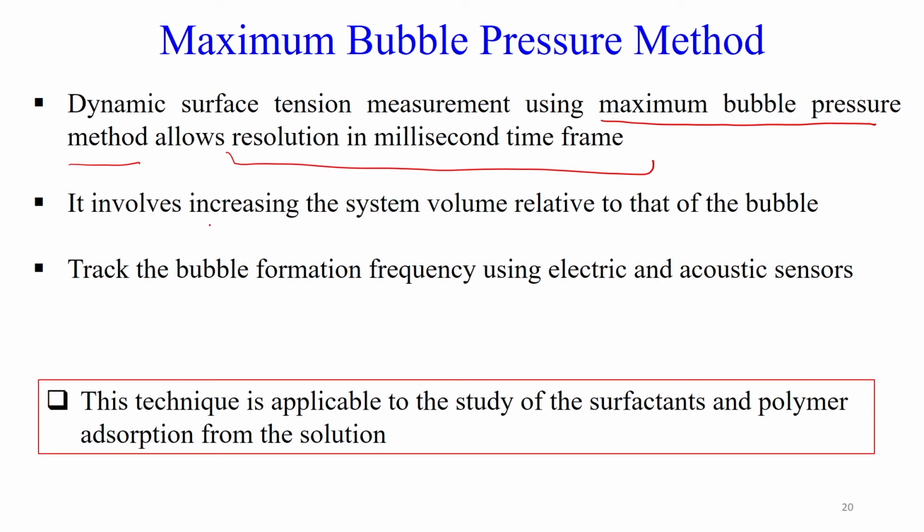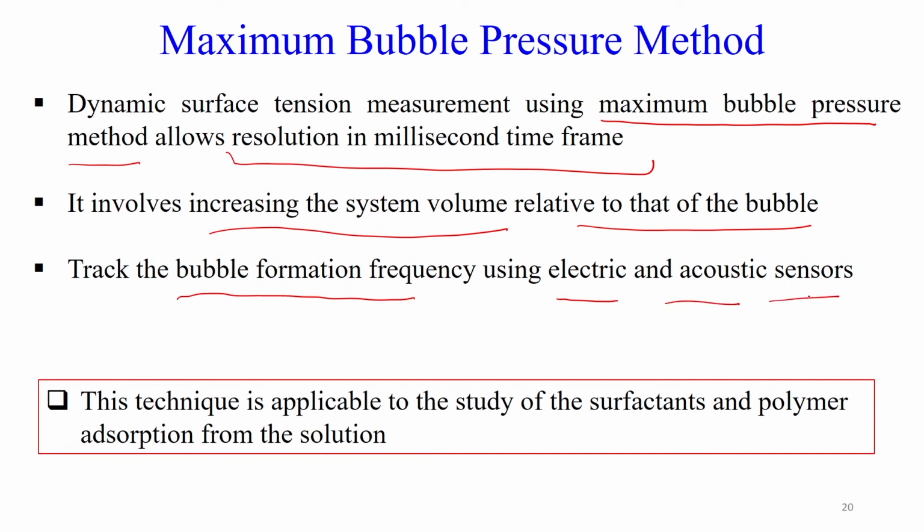If you add the bubbles, there will be an increase in the system volume relative to that of the bubble. If you can track the bubble formation frequency, and in order to track it, we have to use some electrical or acoustic sensors. Once the bubble formation is known, you can see the maximum pressure required to form the bubble, and as well the size or radius of the bubble.